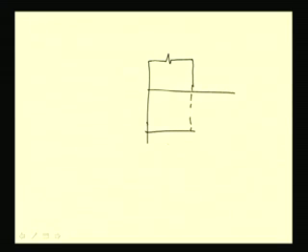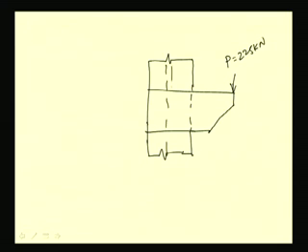So, this is an example, say one bracketed connection has to be made which will pass the load to the column, and the rivet joint has to be made in such a way that without failure it can pass this much load. Say P is given 225 kilonewton, and the eccentricity is this one, say 160 mm. Now, with this we have to design the connections.